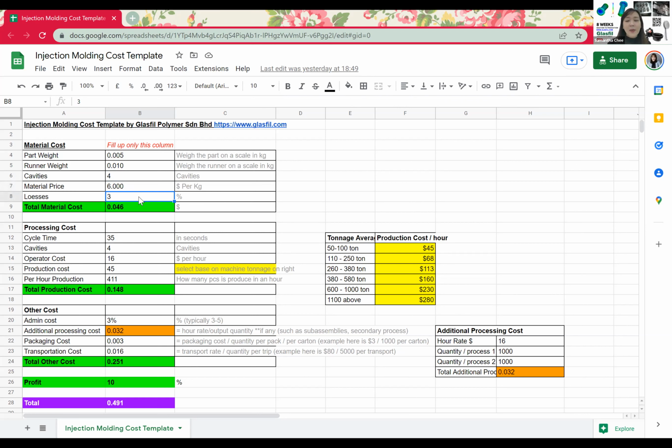And typically, a manufacturer puts in some losses because there are rejects, which you don't purchase, because you only purchase the parts. So typically, the factories will put in losses of around 3%. And these make up the material costs. If you notice, for a weight of around 5 grams to 15 grams, your material cost is around 4 cents.